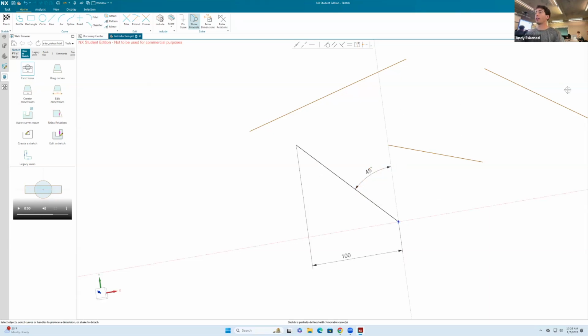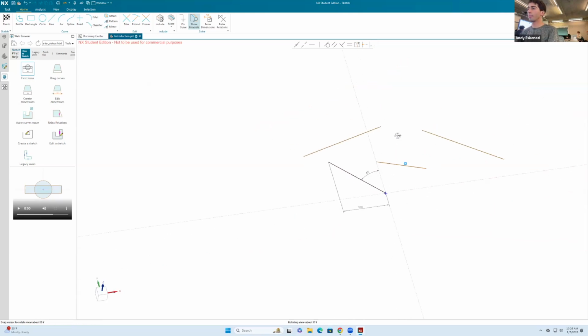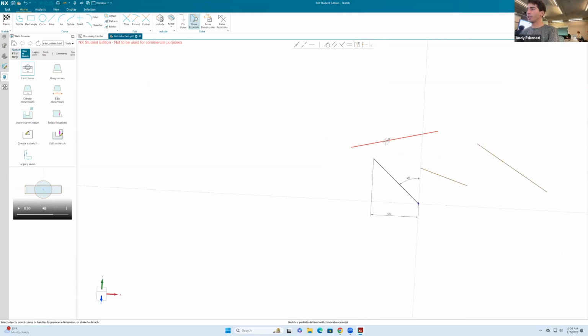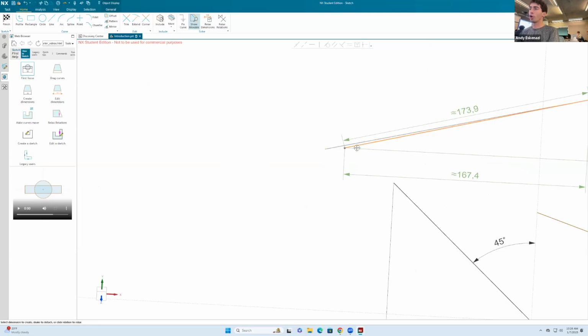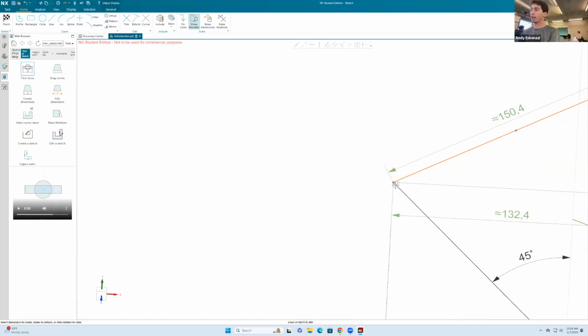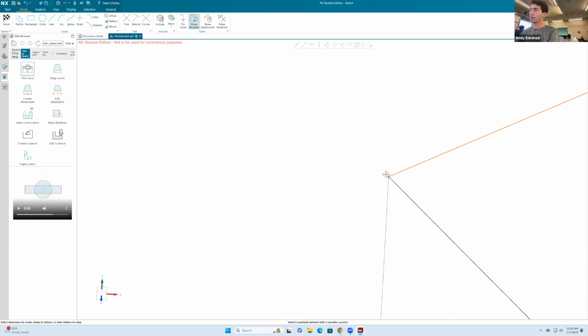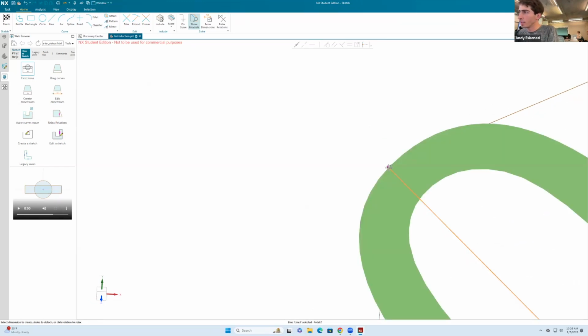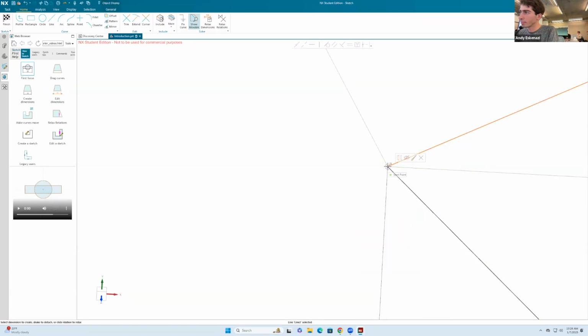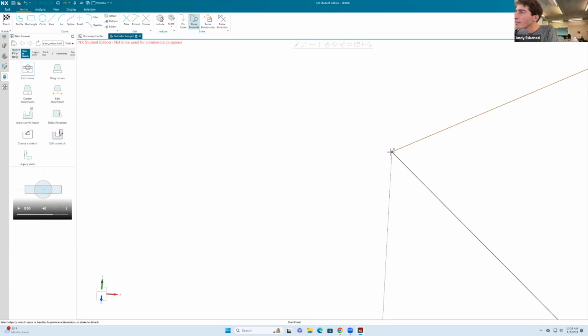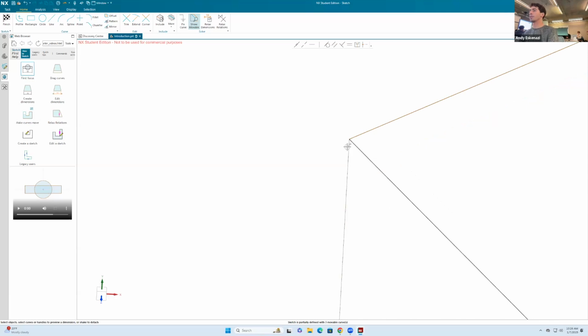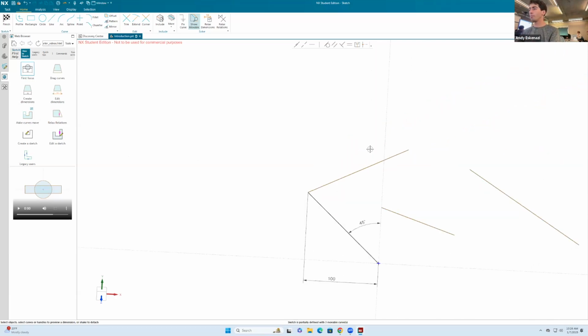And now you see how this line is fully defined, because now we only have 3 remaining right here. What I can do, for instance, is bring this line, click on this point, which is one of the vertices, and make it coincident. I just dragged it in there. I can also click again on that point, if I'm not mistaken, wait until it becomes purple, and I believe I can drag it away. Let's see. Well, it doesn't work in here, but it doesn't matter. Sometimes you can also break the mate in there.